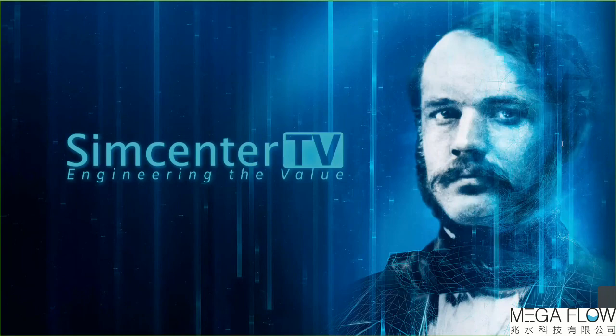So I guess your question is about having a small cylinder compared to an MRF setup only between the rim spokes. Well, in an ideal world, when you have no tangential inflow, I would say the difference should be negligible. At the end of the day, there might be a small difference between these two setups, but it's really negligible. The case that I showed with the big MRF volume extended a lot into the main airflow. So between the small cylinder setup and the setup between the rim spokes, the difference should be negligible in my opinion.